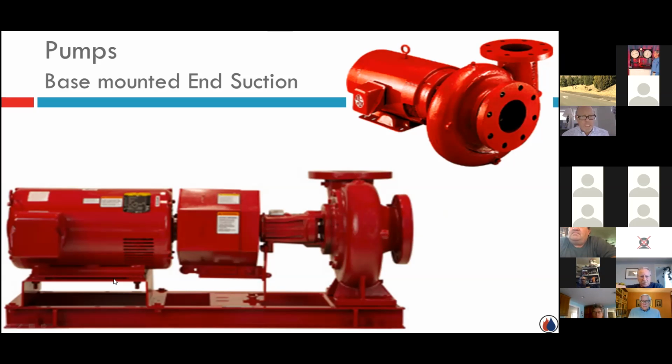You've got your motor sitting here on the motor brackets. You've got your coupler that's connecting the motor shaft to the bearing assembly, and the impeller is inside the wet end of the volute. It's very popular, very common in commercial applications. You'll see it a lot. Can handle a pretty good capacity.